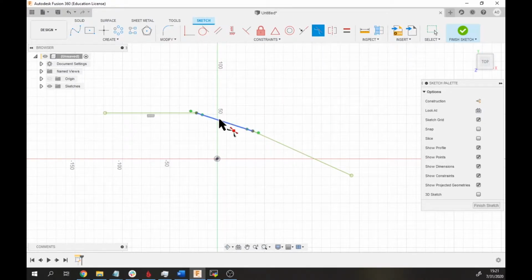And what the Curvature Tool will do is make it so that this is both tangent and follows what's known as G2 symmetry, which is a system that allows you to have a G2 type of curve, which is used in CNC machining and is beyond the scope of these videos. But needless to say, you probably won't be using this, but it's a good thing to have a grasp of, if for no other reason than allowing you to create these complex curves without having to make multiple tangent arcs and setting them equal and dimensioning them. It's a very simple way of doing this.